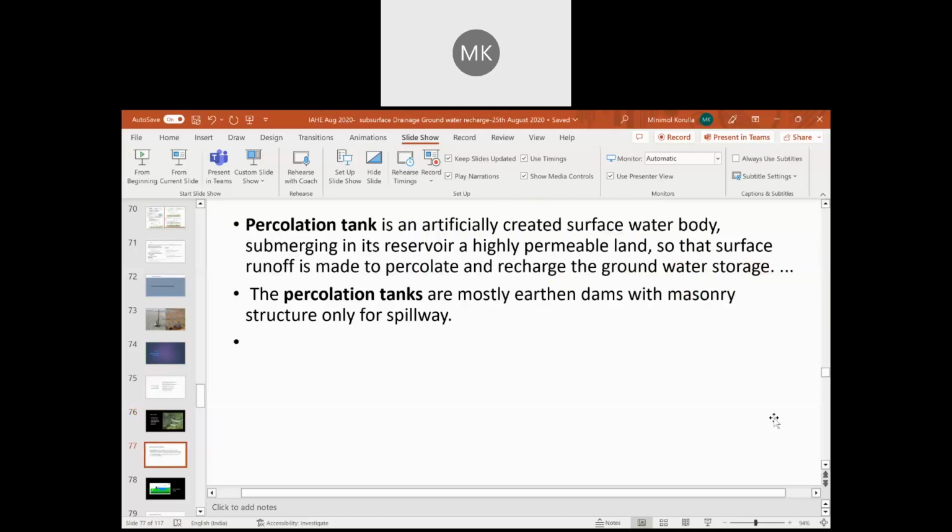The same way, drainage composite also you can do with manual calculation. Where the software will be useful is especially when we are going for landslide correction, where we may have to really see how the subsurface flows and how the seeping will happen, because there will be impermeable layers, permeable layers, and different types of permeability characteristics. So we need to understand through which layer the seeping will happen.